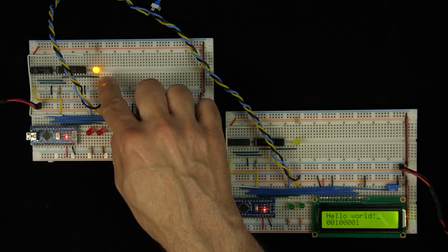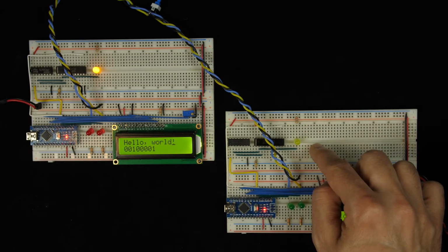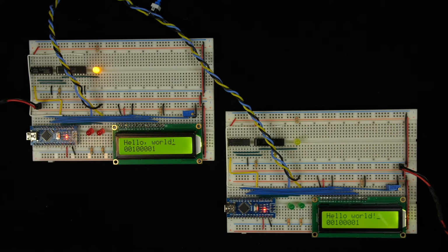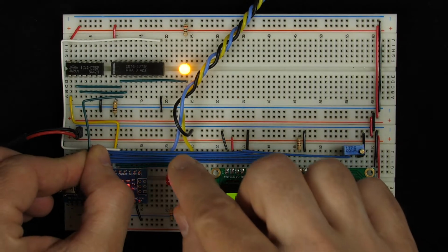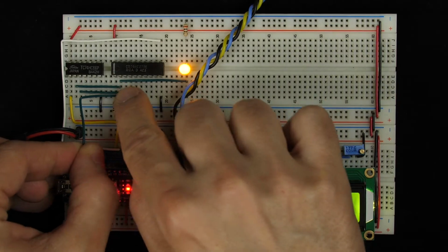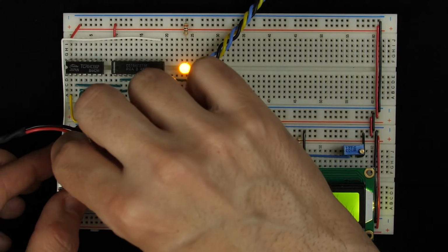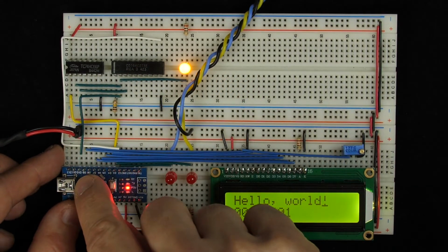So how do we get the value of this parity bit sent over to the receiver? Well, I think the easiest way is to have the Arduino just read the value of the parity bit and send it the same way it sends the rest of the message. So to get the Arduino to read the parity bit, we can hook the parity bit to an unused data pin on the Arduino. So I'll connect the parity bit, which is the output of the D flip-flop here, to pin D10 on the Arduino.